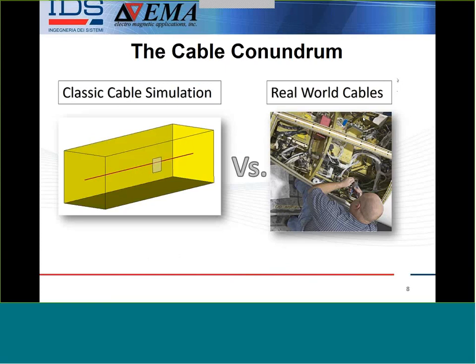Just by looking at it, in your EM intuition, in your gut, you know that you're not going to get the same answer from these two. Obviously, those cable harnesses, that bay has a huge fill factor. By that I mean you're going to have greatly more losses from fields in there. The cables are going to branch, so you're going to break up resonances.